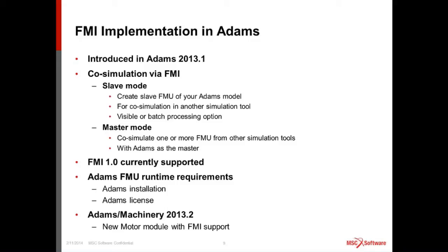In master mode, you can bring in other FMUs from different software into Adams. And during the co-simulation, Adams will call the other software, and the two solvers will communicate at a certain time interval. Currently, only FMI 1.0 is supported. And an Adams FMU requires an Adams installation as well as an Adams license to run, even if it's a slave FMU that you want to use with another software.